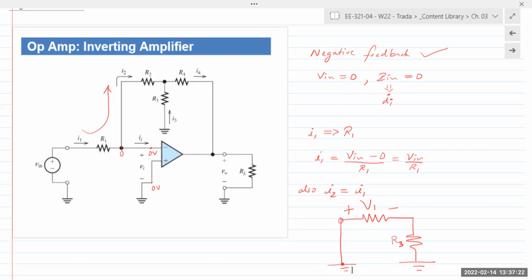If that's the case, then R3, which is physically connected to that same point, and R2, which is connected physically to the inverting terminal, can be considered in parallel, as I've drawn out here. They were already connected here, but now, because of those assumptions for analysis, we can say they share both terminals at their respective ends. So you can consider them to be in parallel.